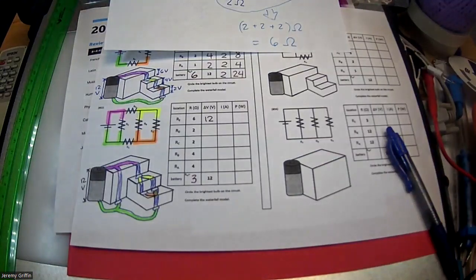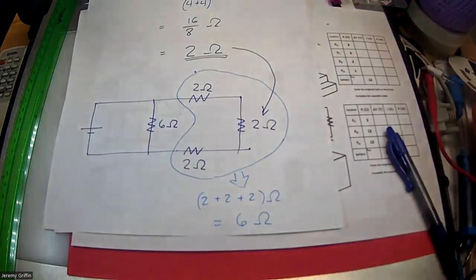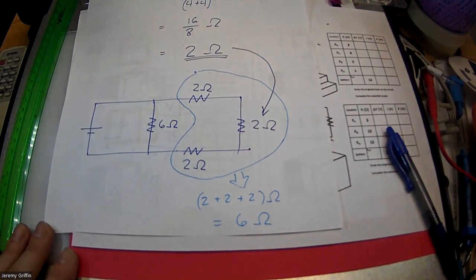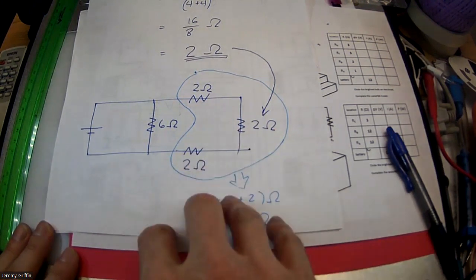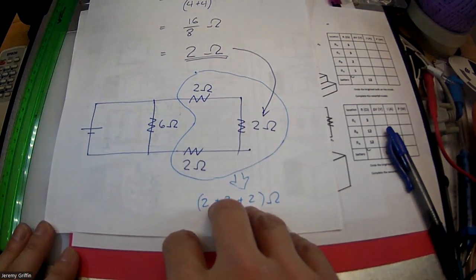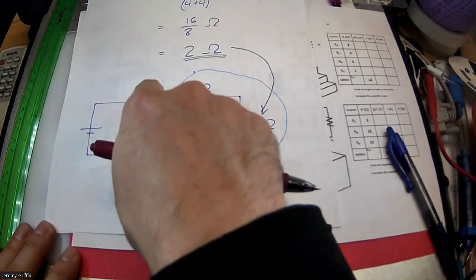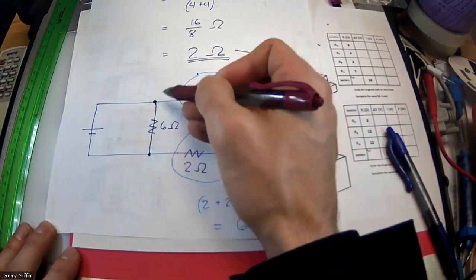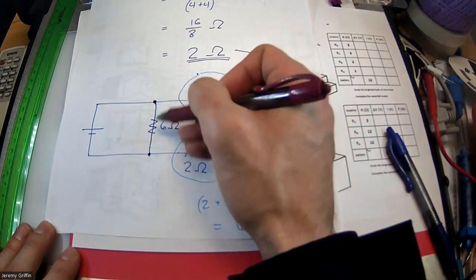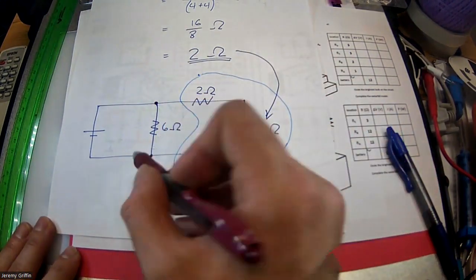How are we going to figure this out? Well, remember I said to hold on to your middle steps for when you're finding equivalent circuits. This is exactly where that's going to be useful. So this was one of the middle steps. You guys remember that? And I know from here to here, there was a 12-volt drop. So that means from this node to this node, there's definitely a 12-volt drop. Whether you go directly across this resistor E, or if you make a round trip around here, either way, it's got to be a 12-volt drop, right?